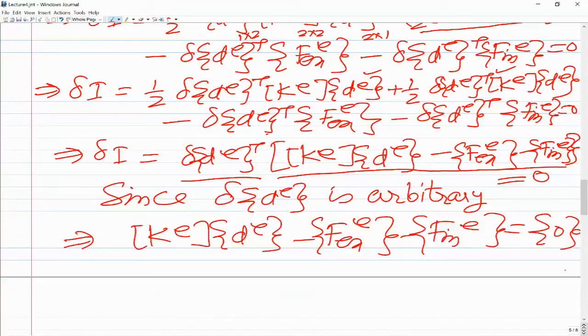Of course, ultimately in the assembly, at the nodes where U is prescribed as a boundary condition, the variation in that degree of freedom will be 0. But otherwise, it is arbitrary, if you have the element anywhere. Okay, sir. Yeah, we are talking about the element anywhere inside the structure.